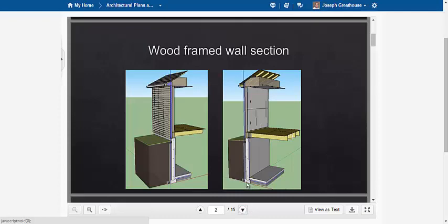We can see that this is our concrete foundation wall that sits on top of a concrete footing. You guys are probably familiar with the word footing before. Again, that sits at the bottom of the wall, gives the support for the entire building. Then off of that footing, you can see that our basement floor sits on top of 4 inches of rock, some insulation, and some vapor barrier. And when we get to the section views of the actual print, you can see the detail in that a little bit better. So that's on the inside of the basement.